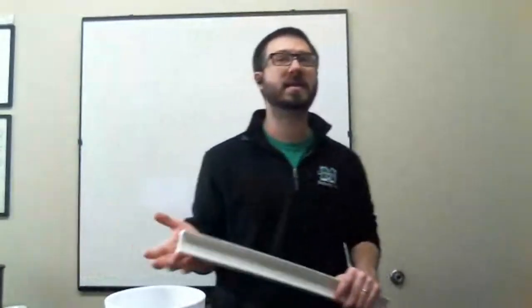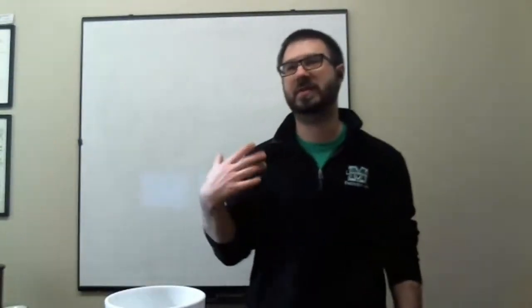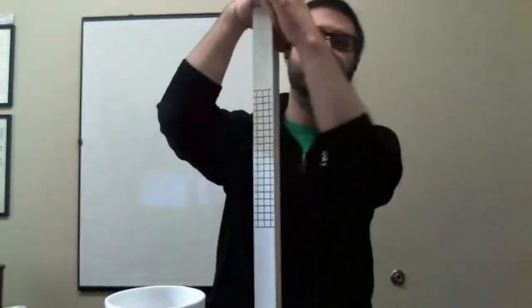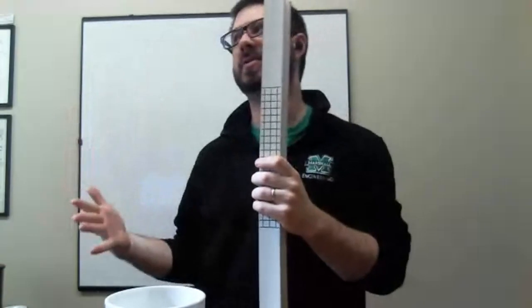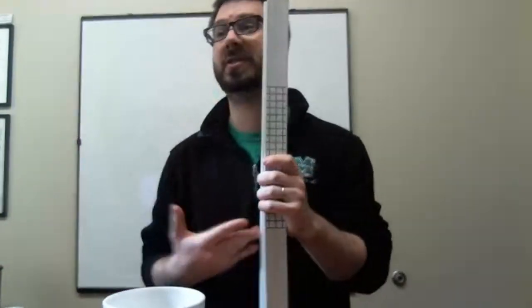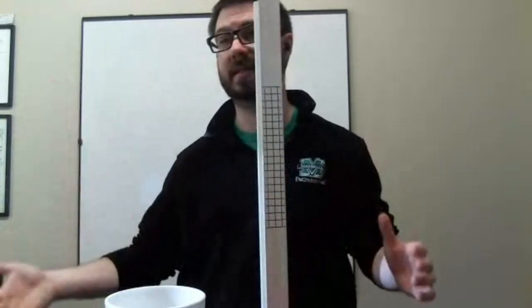The way you said that was excellent, because what you did just there is define two limit states. You defined failure under general compressive stress, where we might ask what the limit would be. Maybe the limit is when the metal reaches its yield stress. So compressive yielding would be a limit state.